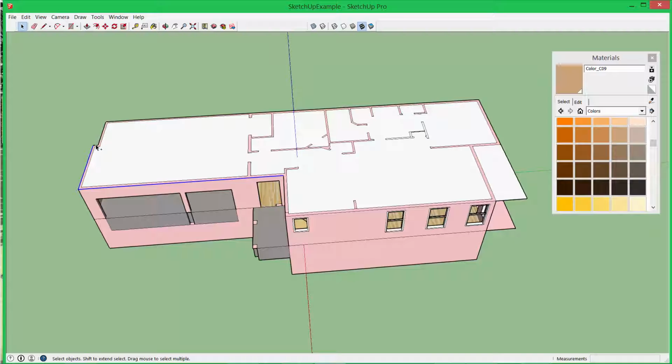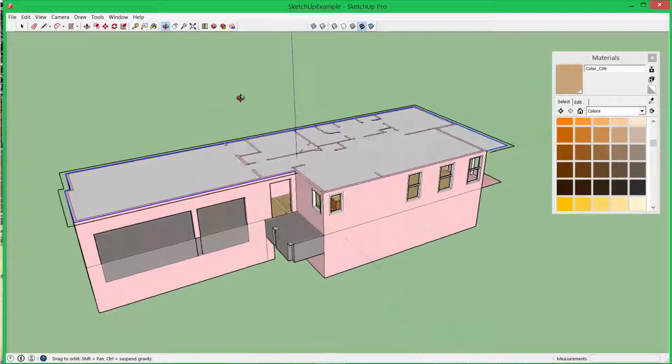Hold the control button down because it's multiple selection, and you want to see this line go all the way over. We're going to select this and then this, and this is going to be a roof that's overhanging here. So I could close this down, but keep on holding the control button down. I'm going to do that later, and I'm going to hit my offset tool that we did with the window, stretch it out, and we're going to put 12 and enter for a 1 foot offset. So 12 and enter. And now I've got my 1 foot offset.